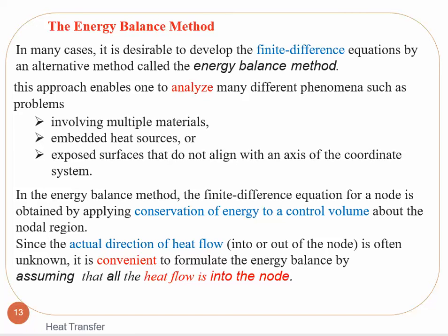The energy balance method. In many cases, it is desirable to develop the finite difference equation by an alternative method, the energy balance method. This approach enables one to analyze many different phenomena such as problems involving multiple materials, embedded heat sources, and exposed surfaces that do not align with an axis of the coordinate system.